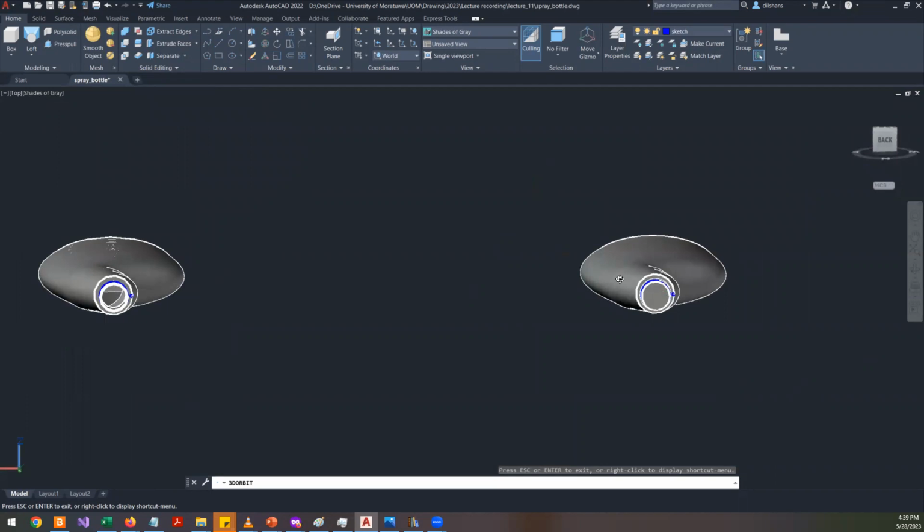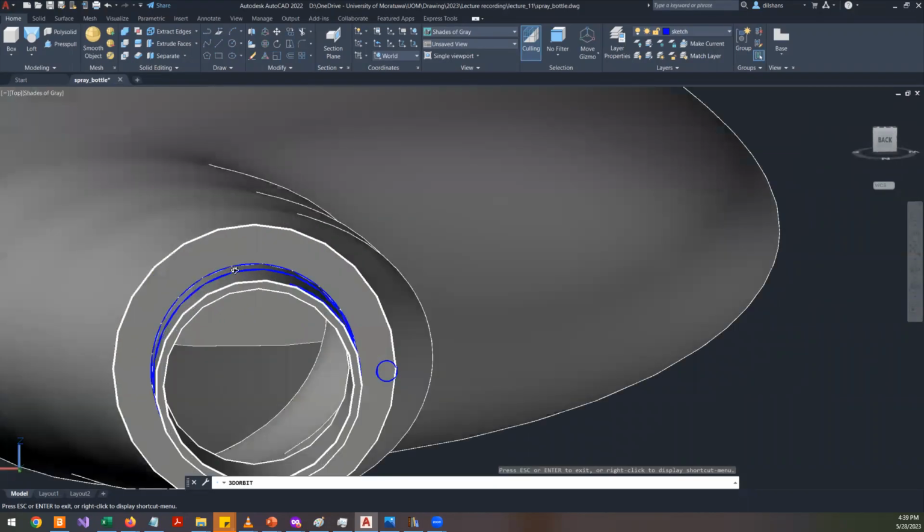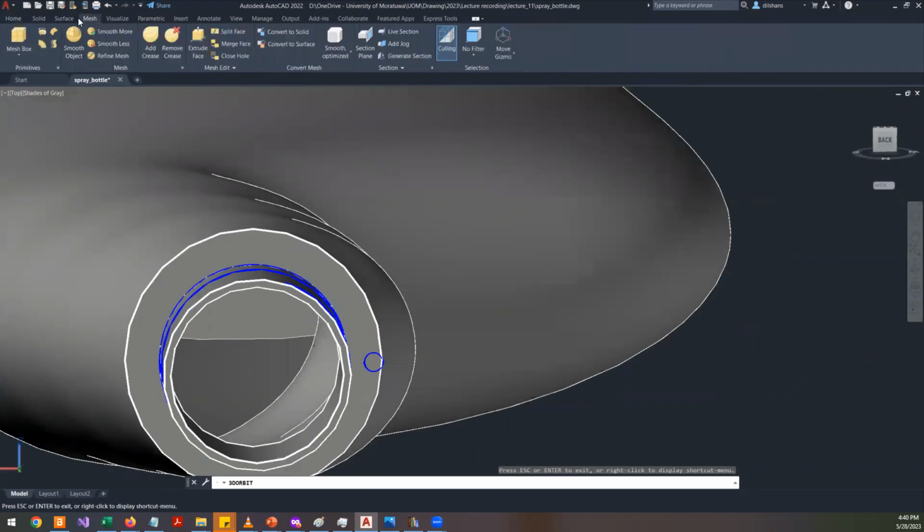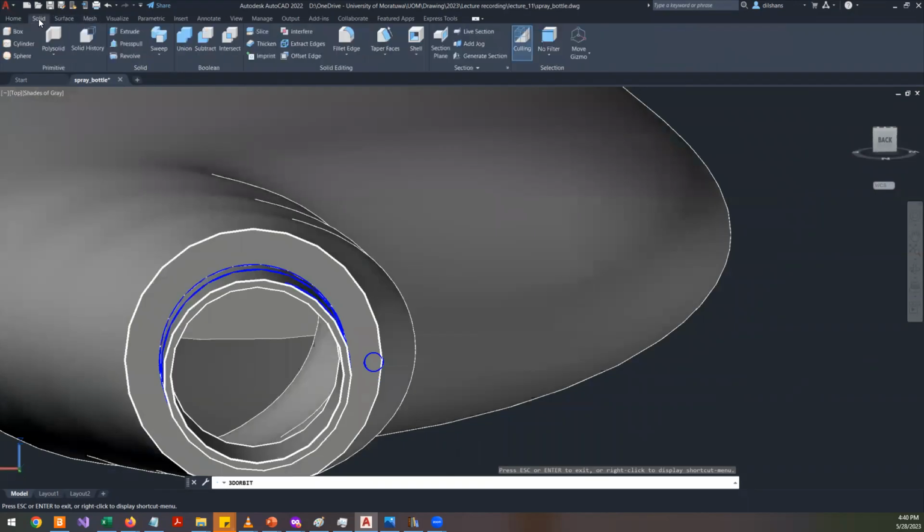So it will not have the proper thickness in some places. So you apply the fillet, and the final operation would be the loft command. Sorry, shell command. Not a command, it is an operation. So you can find the shell under solid, and here we have the shell.